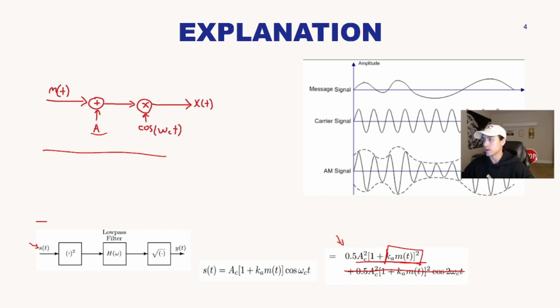In this other example, it's the same thing that we did in the problem. You multiply by 1 and -1 on this message signal, so you get something like a DSB-SC. And then to make it amplitude modulated, you shift it up by an offset of A, and you receive something like this, which is the envelope for the signal. And then the envelope for the signal times the carrier signal results in the amplitude modulation that you see here.